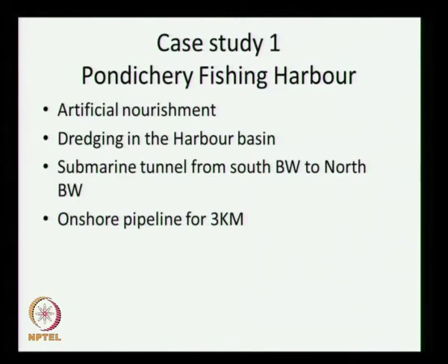So for this artificial nourishment, we dredge in the harbour basin, and there is a submarine tunnel from the southern side to the northern side. That means you pump the sand below the seabed using a submarine tunnel, and you lay a pipeline on the onshore for about 3 kilometers and dispose the dredged material.